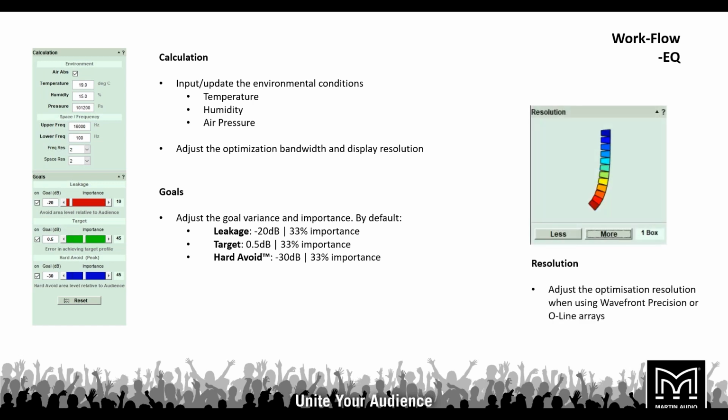If you're using a Wavefront Precision or O-line array, you'll have one more tab here, which is resolution, because those are systems with scalable resolution. And this is where you can adjust what kind of resolution you're using with your PA.